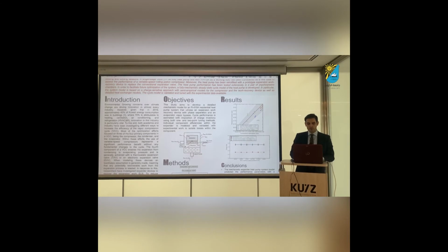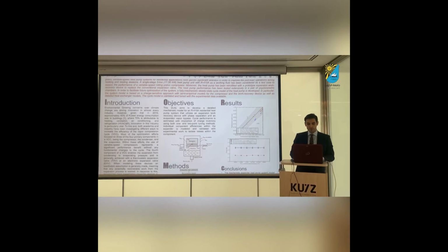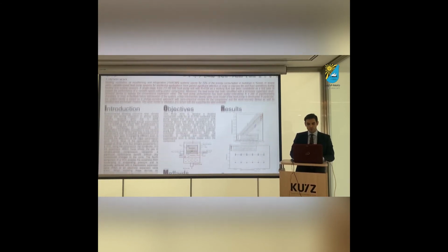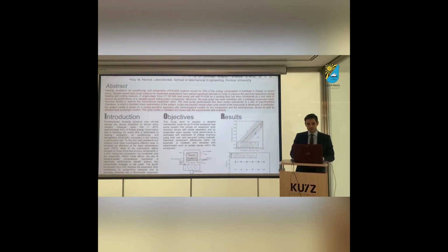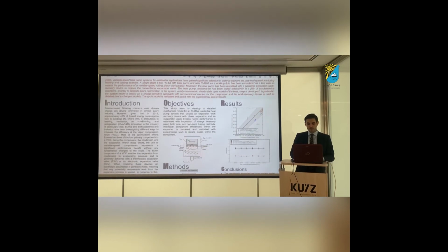The liquid goes to the evaporator, so we're flooding the evaporator. At the same time, the gas is bypassed into the exit of the evaporator. As we inject refrigerant through the nozzle, the turbine rotates and we can harvest the electric energy generated